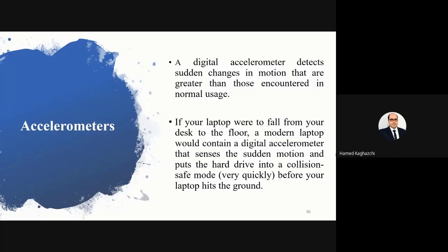When this change is greater than a normal one, which is defined in your notebook for the accelerometer, it reacts. Now, when your laptop falls from the desk to the floor, the sensor detects this sudden motion and puts the hard drive into a collision-safe mode very quickly before the laptop hits the ground.